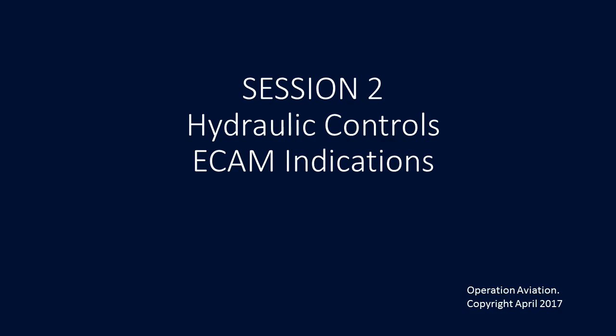Another note on the PTU: if for whatever reason it fails after the automatic testing, the ECAM will not inform the crew. The crew will be aware of the failure only if there's a subsequent green or yellow pump failure that occurs. Then the crew can view that on the ECAM HYD systems page. They'll be able to see it then.